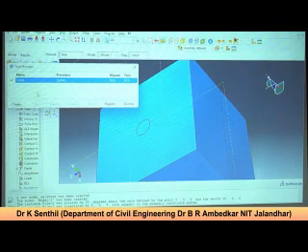The second step you have to create for the gravitational force, because it's a force, it's a gravitational force, right? Then the third step we have to create for the external force. As the professor was suggesting, you apply some live load. It's maybe the weight of the superstructure or the load reaction force that comes from the superstructure. I think you have solved one problem with a 25 ton load acting over the pile, right? So we will create 3 steps.